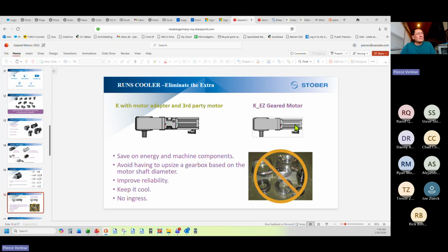You may be able to get the motor only from the manufacturer that did this, but you can't go to another manufacturer. Here, the servo flanges and shafts are relatively standardized. I'm going to say relatively because they're not as strict as the NEMA and IEC regulations for induction motors. I've seen certain square flange servo motors with different size shafts, for example, different length shafts.